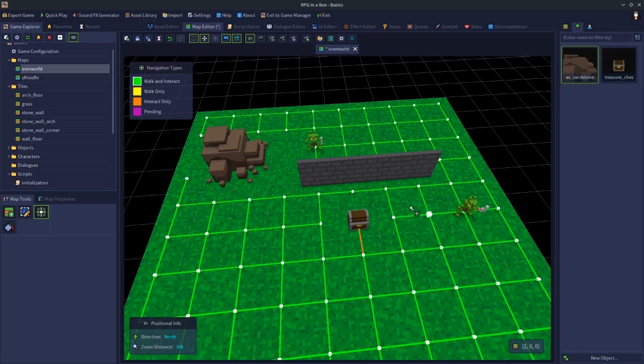To delete navigation, you've got 2 choices. You can either right-click on one of these green pulsating white squares and then drag the mouse back like that. Or you can just hover the mouse over one of the pulsating squares and press the delete key.